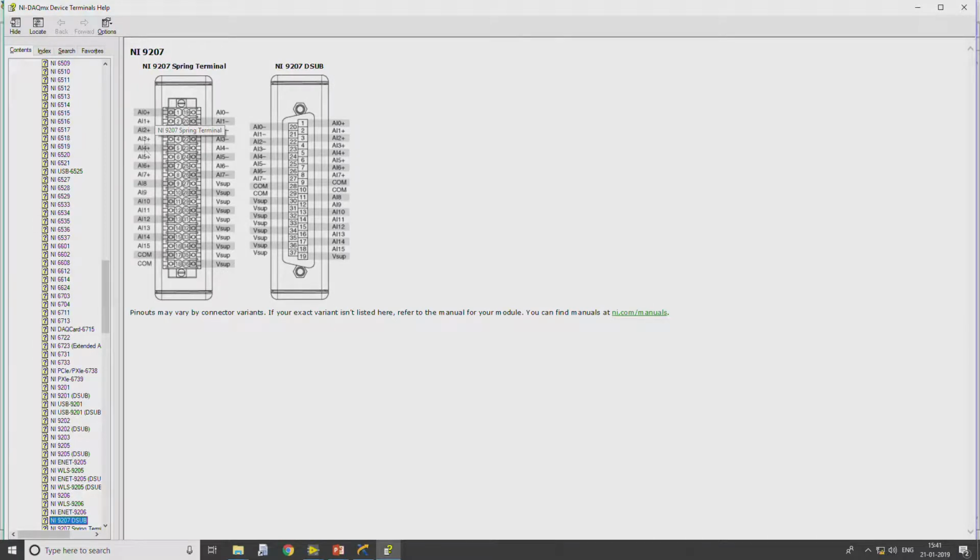The first set is AI0 to AI7, which can make differential input, and it can work for acquisition of analog signals as well as current. It can also be used as a power supply, but it cannot provide enough current or voltage to drive any circuit.